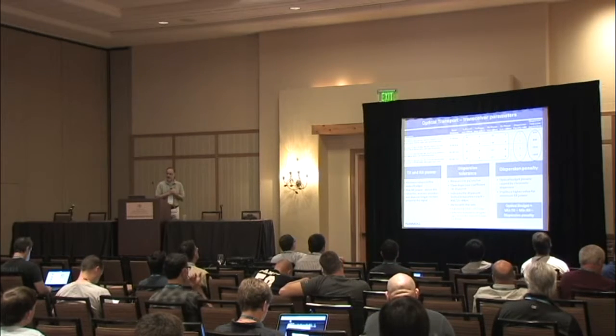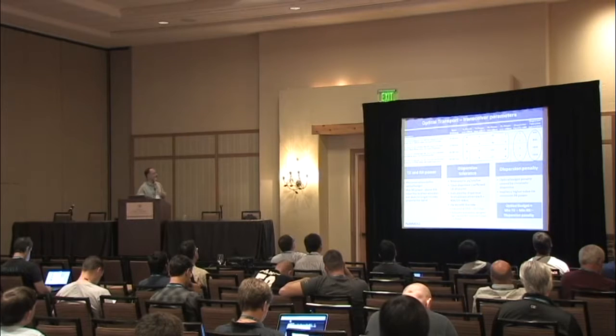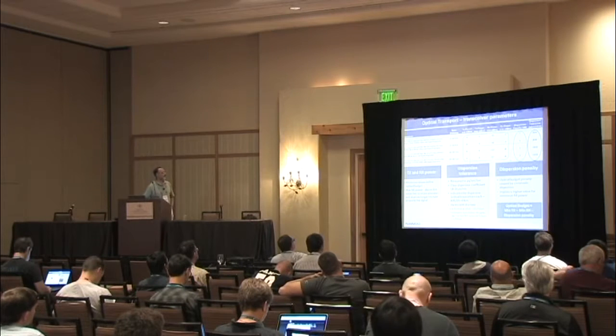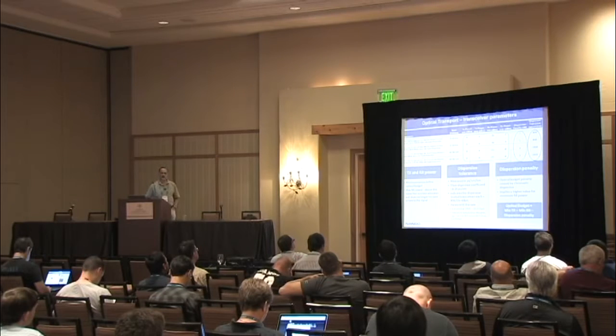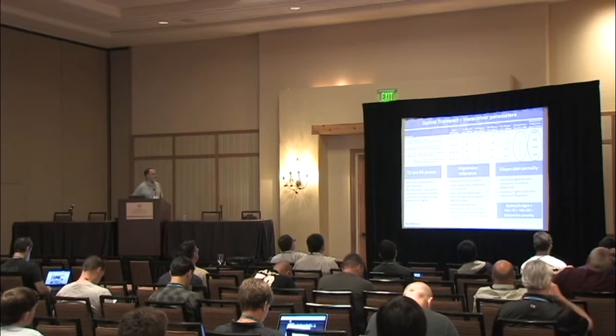Let's look at the transceiver parameters that are basically the basis for our optical budget. Transmit and receive power. Here in blue, I show the 40 kilometer and an 80 kilometer, both 50 and 100 gigahertz. Look at the transmit and receive power, the one in blue. You see that the starting point, the transmit power, is very similar for both of them, for the 40 and 80 kilometer. The main difference is in the minimum receive power. One is minus 16, the other one is minus 23. So that's the difference in reach, or capacity to reach.